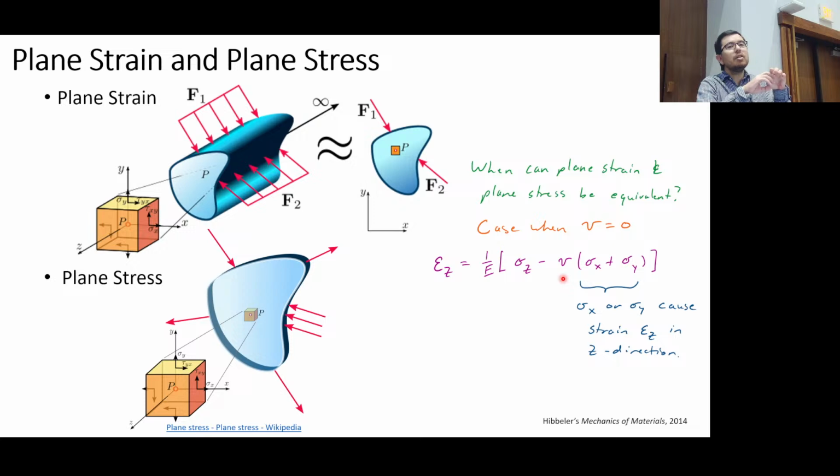These are usually called architected materials, where instead of the cross-sectional area contracting when you pull it apart, it's got little buckling beams and different geometries in it. These are sometimes called auxetic materials, where you pull it and it will actually expand in that direction, which is opposite. Or you compress it and it will shrink instead of expand. So that's not relevant. That's for your good to know file.